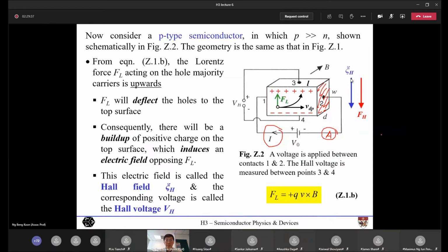In general, when you bias a semiconductor through an external voltage in a single piece of semiconductor, you will not get diffusion. Like in this case, it's everything p-type, so you won't have a diffusion current effect. But having said that, if you put current through a PN junction instead, then you will find that there is indeed some diffusion current that would exist in some part of the semiconductor, which later on Prof. Ang will talk about. Okay. Thank you.